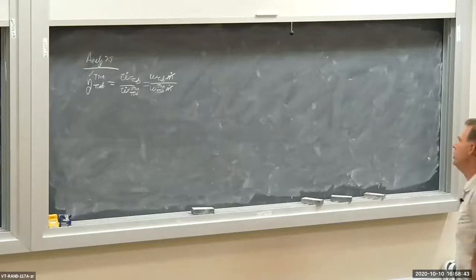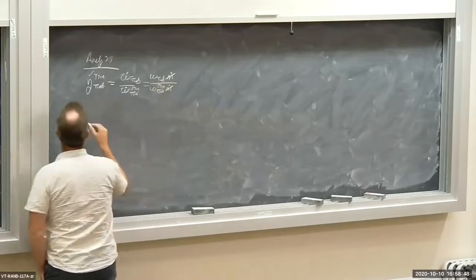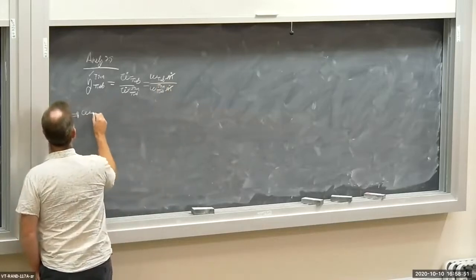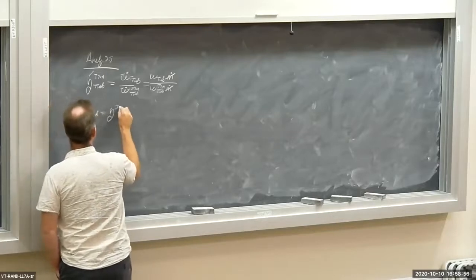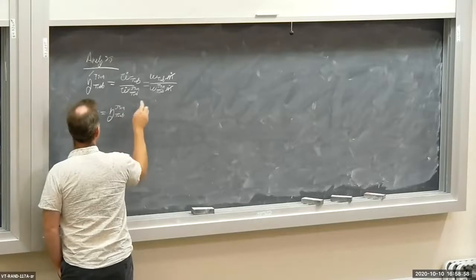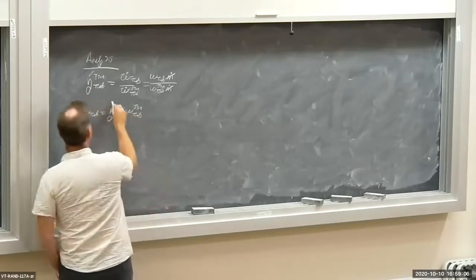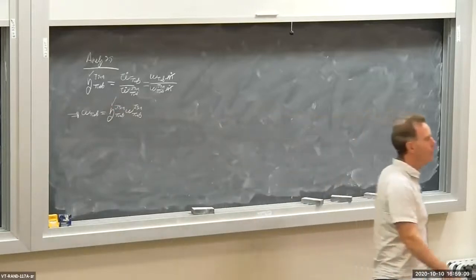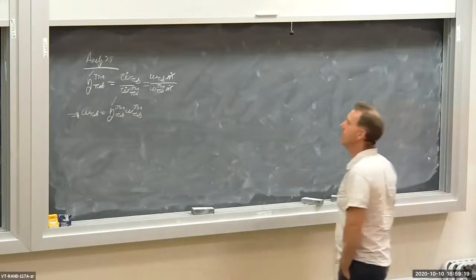Okay, so I want to get W turbine. So this means W turbine is equal to the isentropic turbine efficiency times the specific work of the isentropic turbine. I know the isentropic efficiency. I do not know the specific work for the isentropic turbine, W isenturbine. So I need to find that. Well, how do I find this?